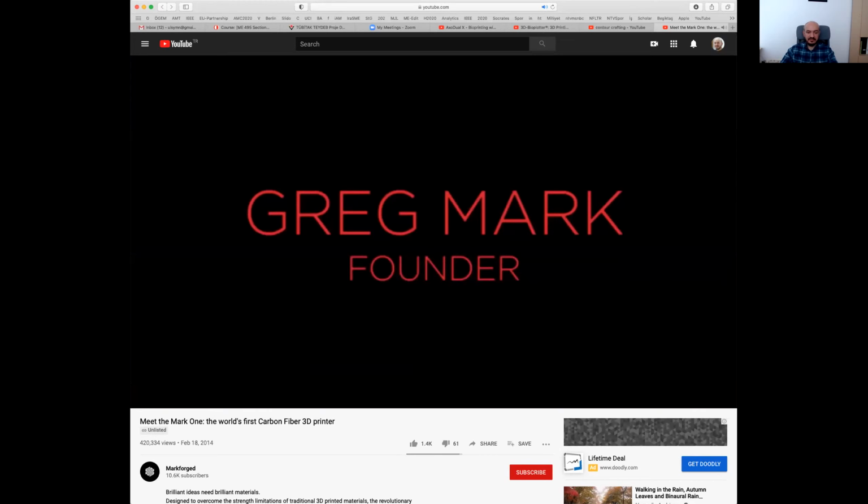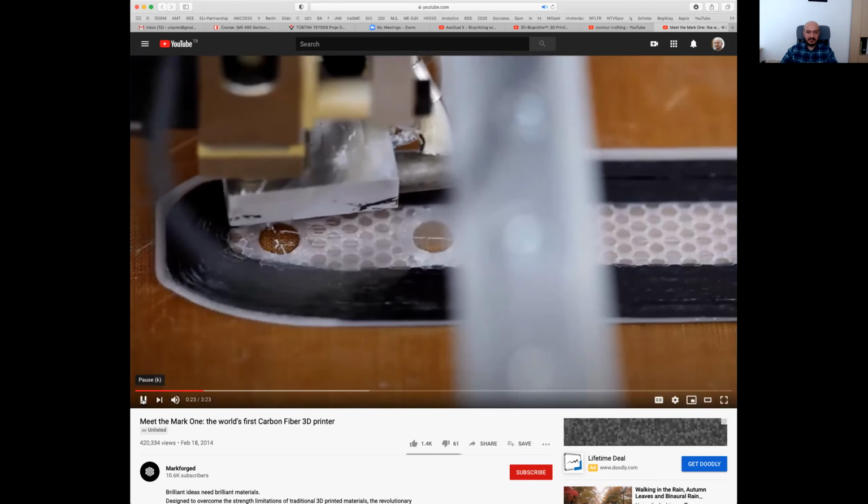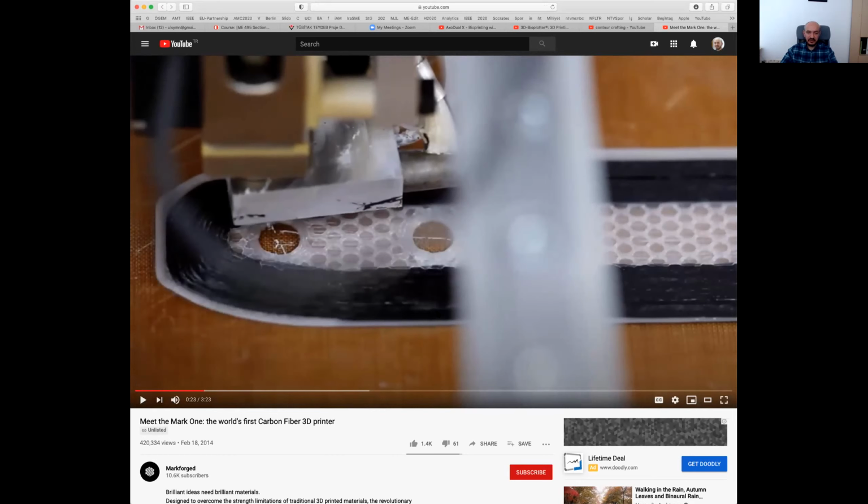And it's also, we have a 3D printer that can print carbon fiber. Yes, that's actually what they are doing. This gray material is probably nylon, and the black ones are carbon fiber. So they are actually using carbon fibers from the spool, and they are extruding it through a similar nozzle. But the thing is that they cannot easily stop and start the extrusion. Instead, they use a kind of scissors to cut the carbon fiber material, and then switch to other materials, switch to the different regions.